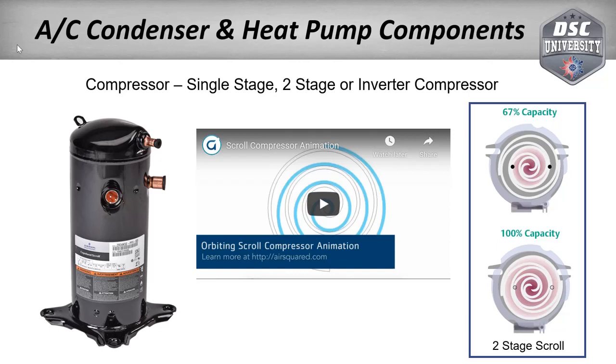Rheem uses these compressors in the 16 SEER heat pump and the 17 SEER AC. So that's why you'll find these in the higher efficiency units, because it gives you the ability, just like we were talking about earlier, on a mild day when you don't have big demand in the house, that unit can run at 67% and probably satisfy your call for cooling. Then when it gets to be an 80, 90 degree day, you may start out running it in first stage, and it runs for a certain period of time and it's not satisfying the thermostat, so then it'll step up to second stage, go up to 100%, and then it can satisfy the thermostat.